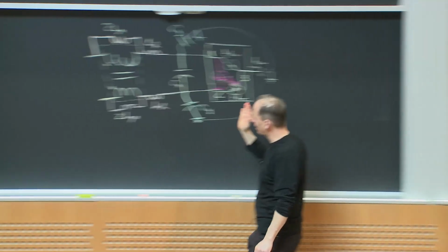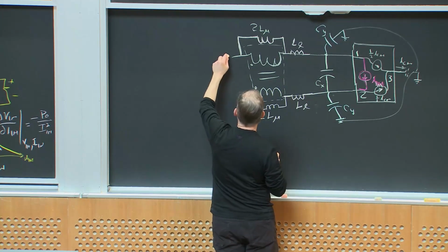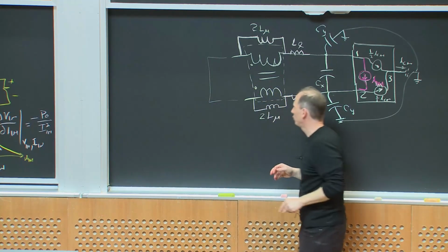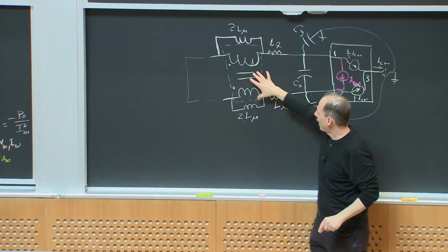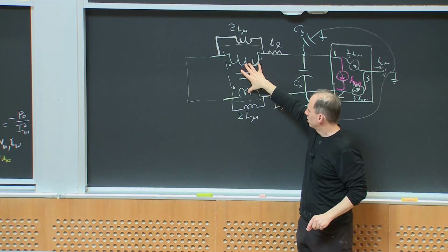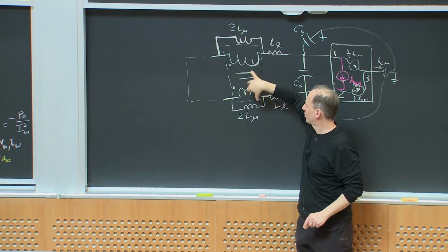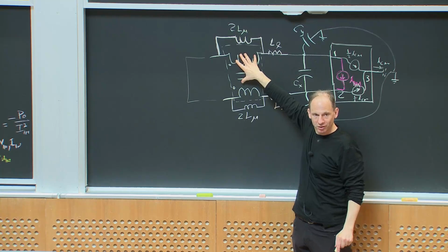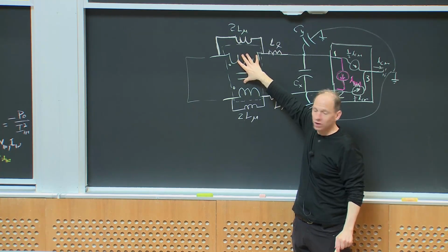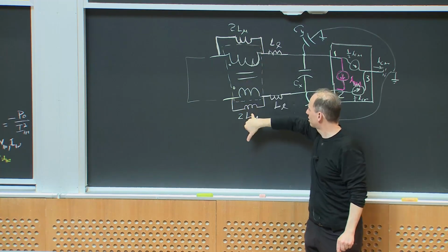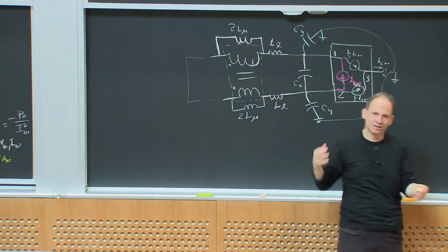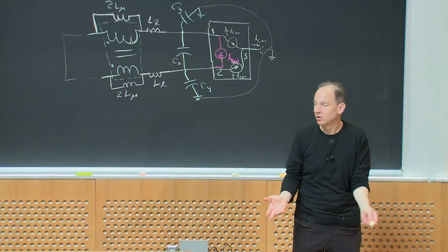If I look back into this, for filter purposes, let me just ignore the source voltage, right? The ideal transformer portion of my transformer carries all the differential mode current, so I don't magnetize the core. So basically, for differential mode, the magnetizing inductance is essentially shorted out, okay?